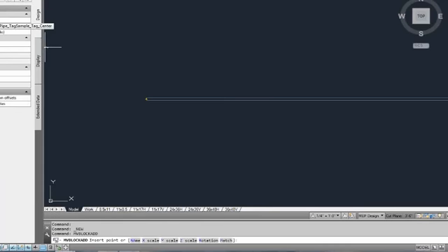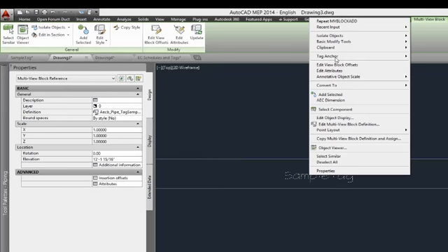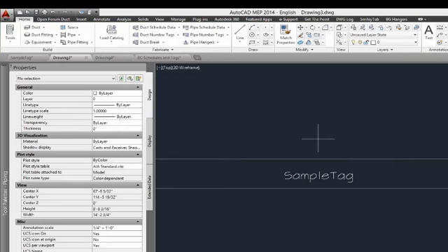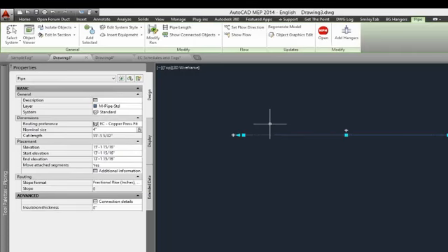Select that, hit enter. So I select that, then I have to come up here and say set object, choose that object, constrain it, yes, and then I now see what the problem is. The problem is that we're choosing a property set that is probably blank on this specific object. So the tag is actually getting placed, the value for that is blank. So it's giving us the illusion that it's not doing anything, when in fact it is. The text is just not displaying anything.